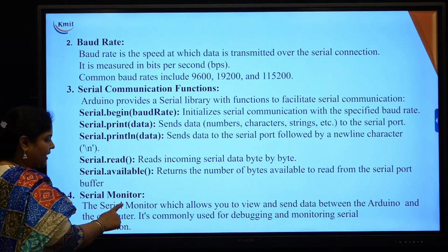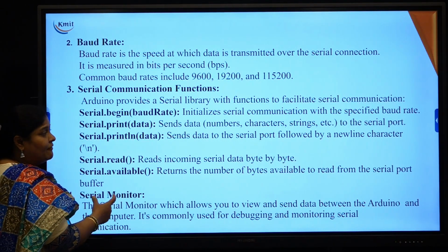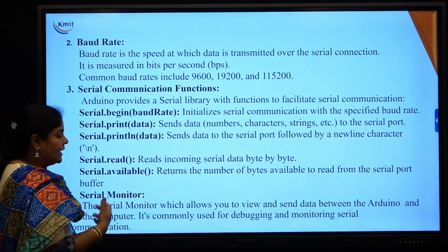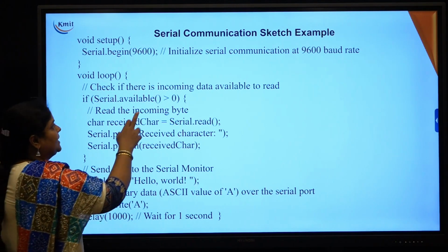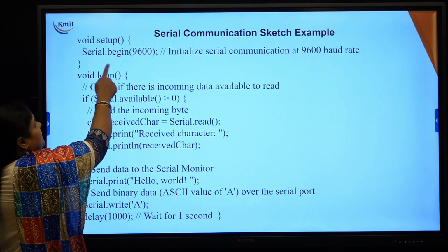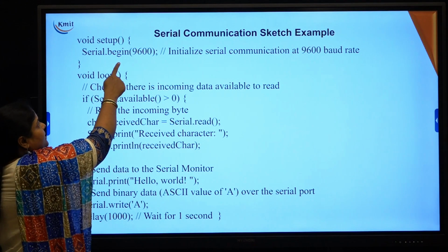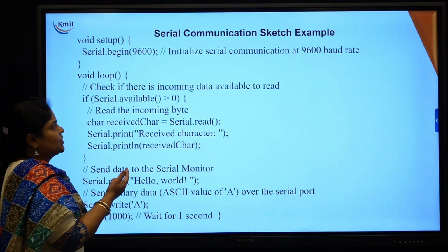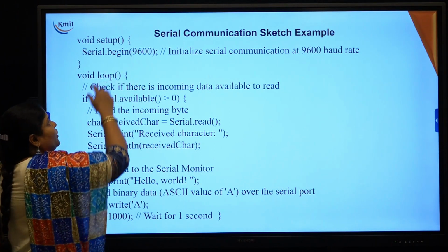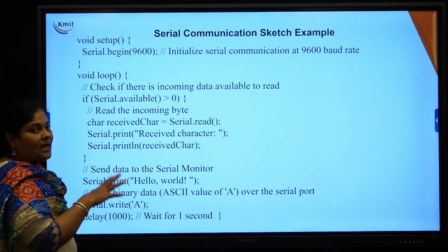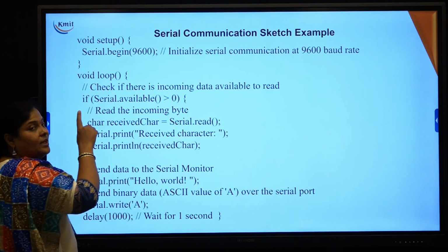Next is the serial monitor. Serial monitor is an important tool where you can see what value is read by the sensor. This is the example for serial communication. In void setup you are writing Serial.begin. This initializes serial communication with some baud rate. You write this in void setup only because I want to execute this method only once.